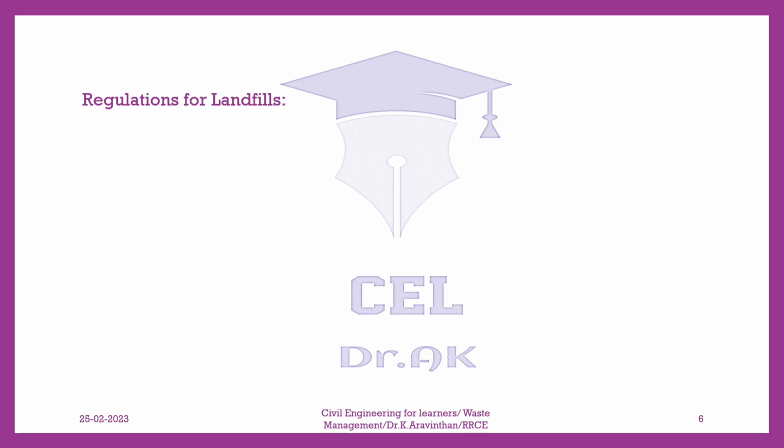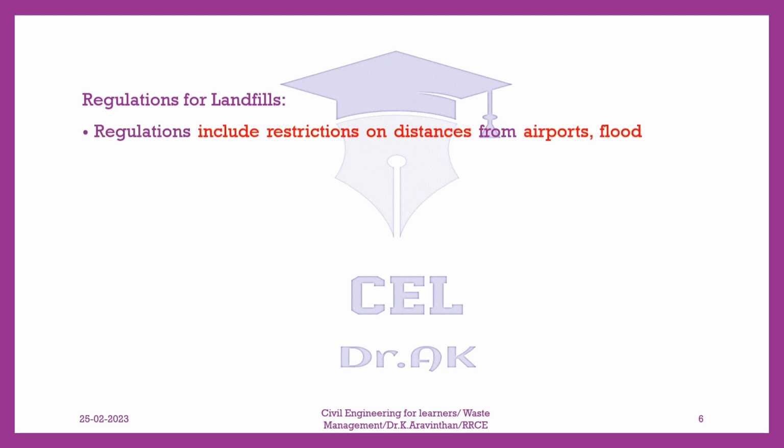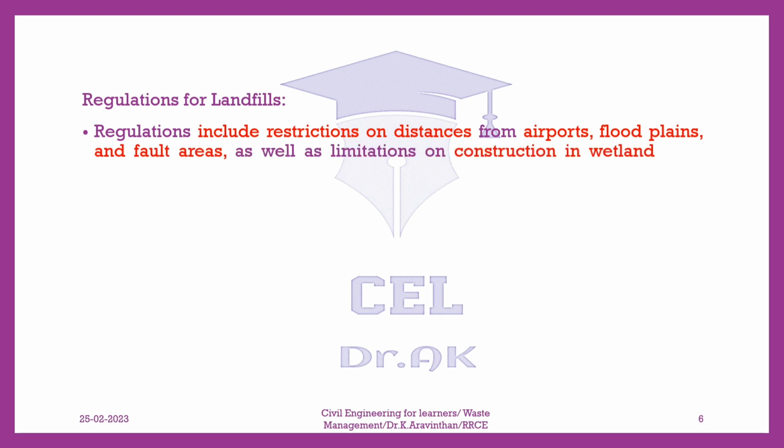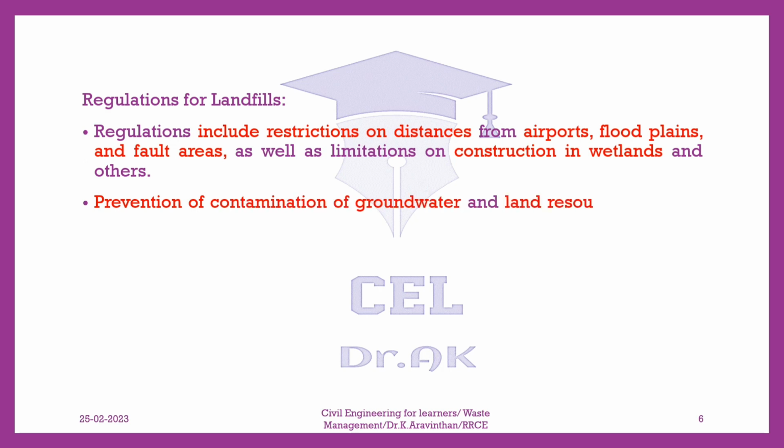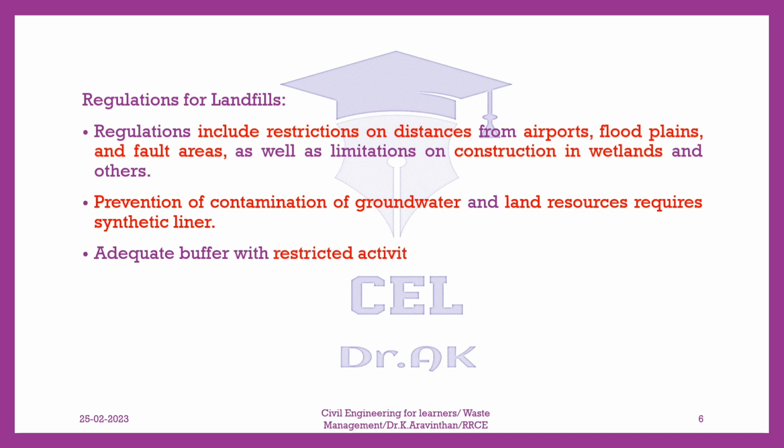Regulations for landfills. Regulations include restrictions on distances from airports, floodplains, and fault areas, as well as limitations on construction in wetlands and others. Prevention of contamination of groundwater and land resources requires synthetic liner. Adequate buffer with restricted activities around the landfill.